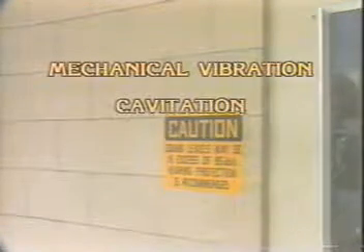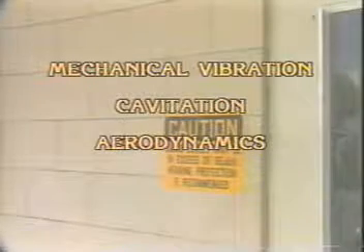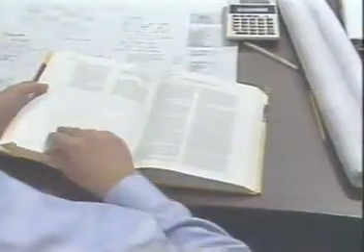But there can be much more involved than the normal operation and costs of business. An improperly selected valve can have an adverse effect on the working environment in your plant. Excessive valve noise is one example. Valve noise can be the result of mechanical vibration, cavitation, or aerodynamic vibration. Studies have shown that excessive noise contributes not only to hearing impairment, but to other physical problems as well.